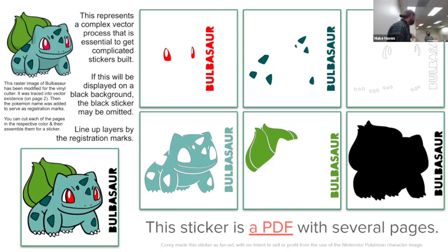Yeah. I mean, there's ways you can cheat around it, but if you're working with a stacked shape and vinyl, PDF is better, because you can go page to page to page, you've got more versatility. Whereas if you're working with single shapes, very often it may be easier to go SVG and just give a reference object, so you don't find out it's out of scale and have to fix everything.